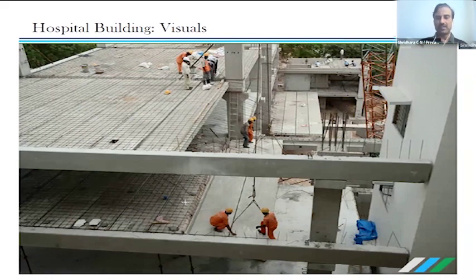This normally requires a minimum of 50 mm thickness. Again, the thickness depends on the span of the slab and the camber we get in the prestressed slabs. According to the camber, the screed thickness has to be defined by the design department.